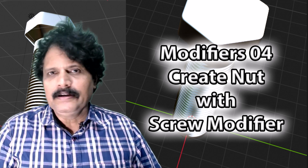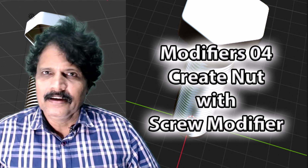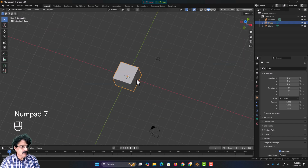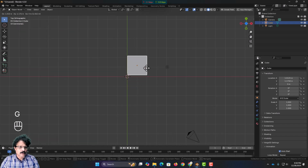In a bolt and nut, we need the threadings, and we are going to create these threadings using the screw modifier. So to begin with, let us come into Blender, and in Blender you have the default cube here. I will select this, press numpad 7, come into the front view, and then I will just press G and move it somewhere here.